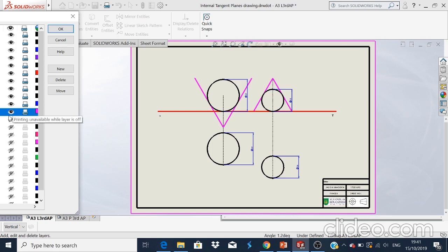These cones are drawn at 60 degrees. So it's this angle here between the XY line and the pink line that is 60 degrees to the ground line. I'll give time now, so I can pause the video and the students can get this drawn. The next step after this is that the points are brought down to the plan. Your two spheres are drawn in the plan.